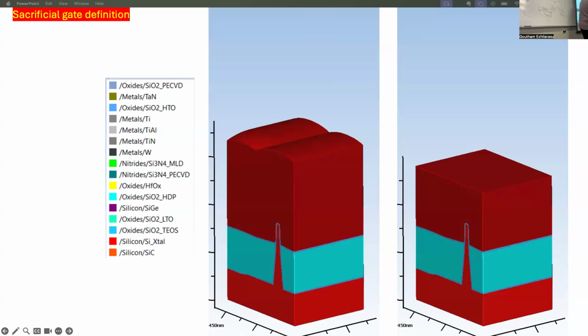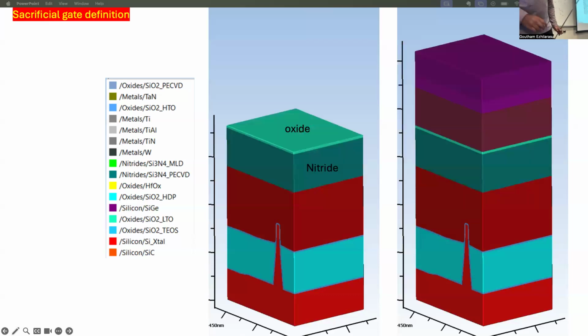So now this polysilicon is for that process. What do you do? We first deposit this polysilicon and we planarize it. We do a CMP, but this CMP does not need a polystop. It's a reference CMP, which means you CMP for a certain period of time till it gives you some thickness, and then you stop. The way you do this in practice is you do CMP for different times, and you do a DOE, and you find out which gives you the right thickness you want.